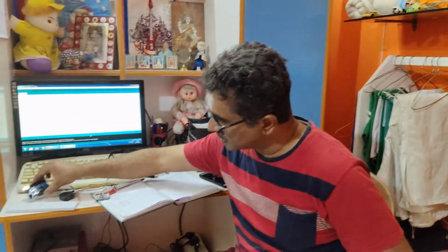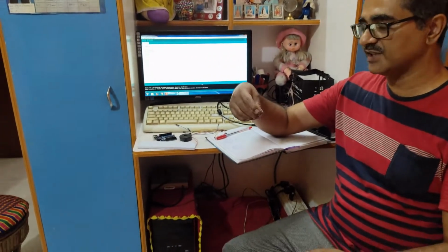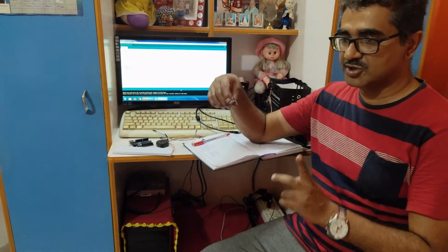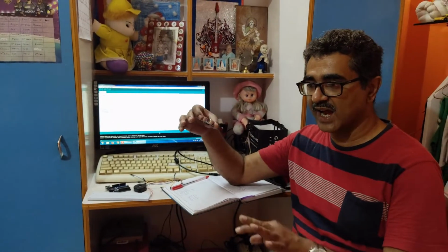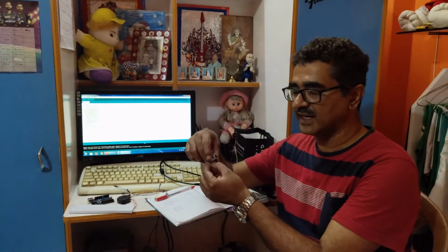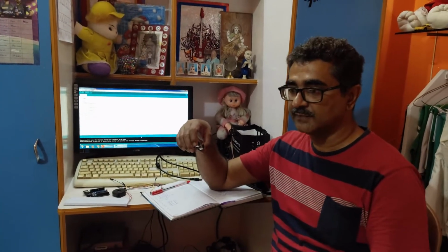Now what is important is the calculation of the distance. Remember, there are four pins which I've already mentioned earlier, and VCC is for the voltage, and ground is for grounding it to the Arduino. In the trigger pin, we are going to set it high for 10 microseconds. Now it's going to emit an ultrasonic sound, which is an 8 cycle sonic burst.